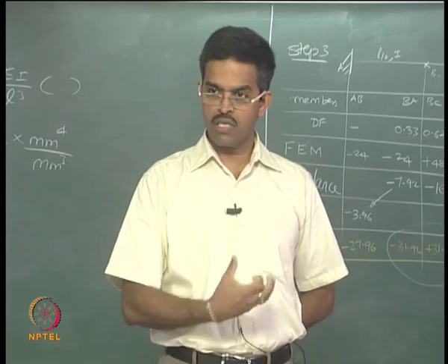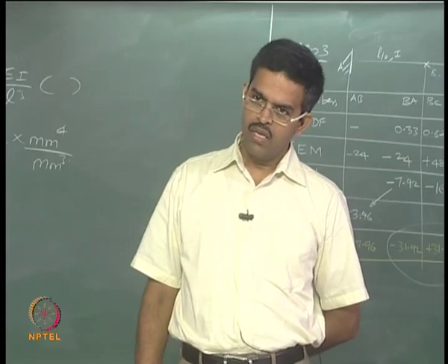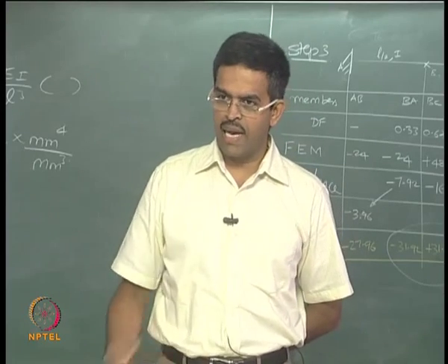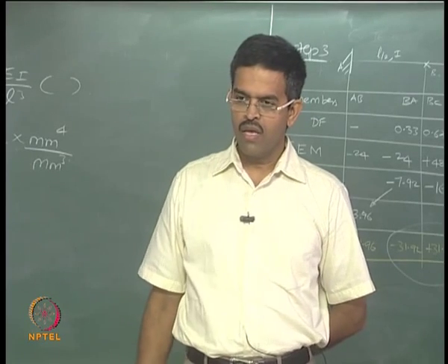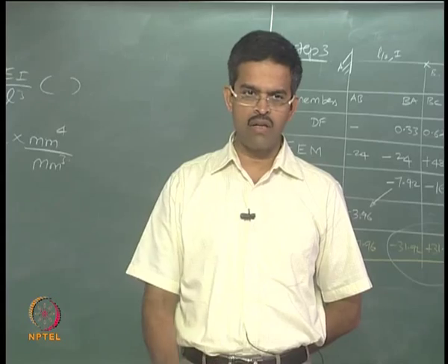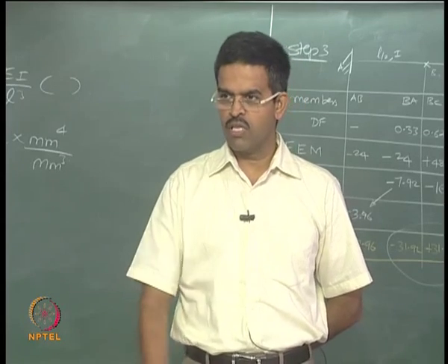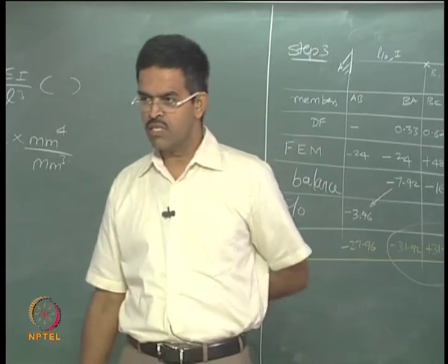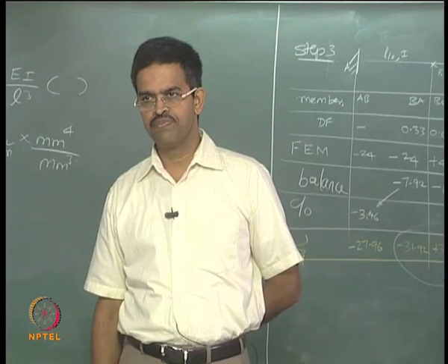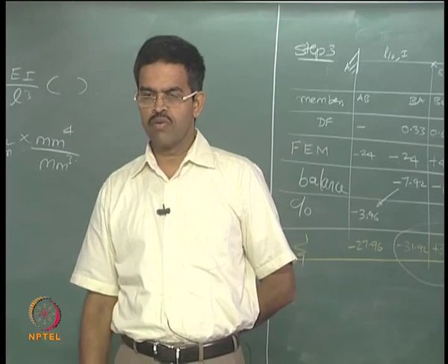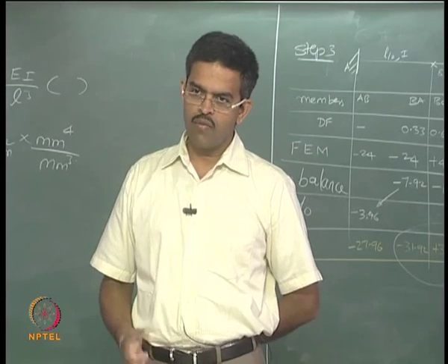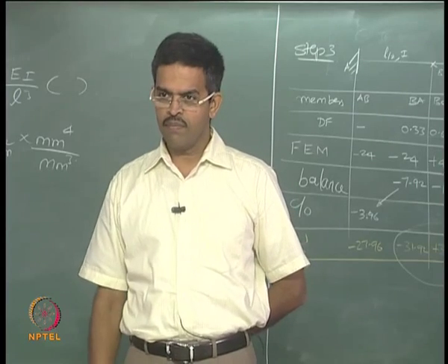So, they model the structural system in the software, let the software arrive at the k and m for the given problem, and pathetically you do not know whether it is right or wrong. You simply keep on doing the analysis and get the results, which is wrong, because a form is innovative, you have no basis to derive k and m.